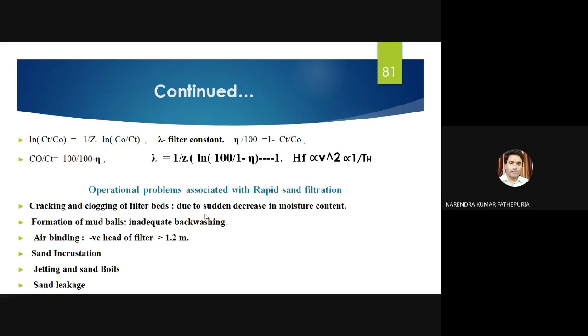During wash, there may be some lateral pressure between the point where the water breaks through and the sticky mud is pushed into a lump or ball, from the size of a pea up to 2 to 5 centimeters or more in diameter. A 50% expansion of sand in washing is effective in minimizing the production of mud balls. Formation of mud balls can be reduced by providing an adequate backwash of the filter media and disinfection of the filter media.